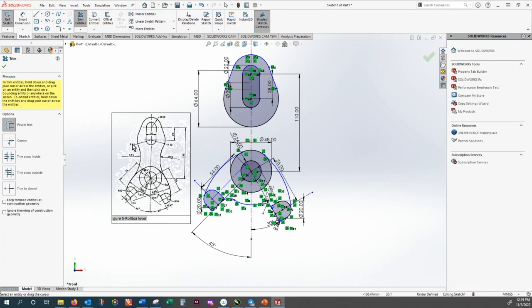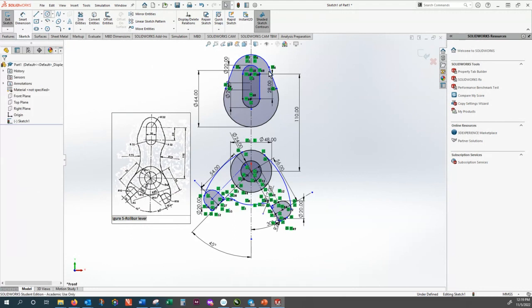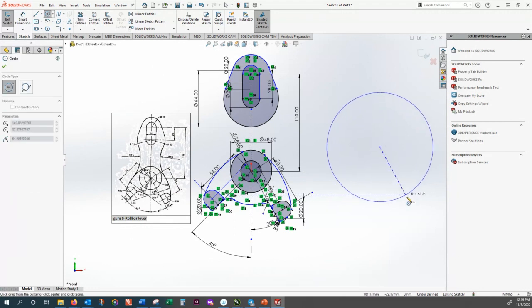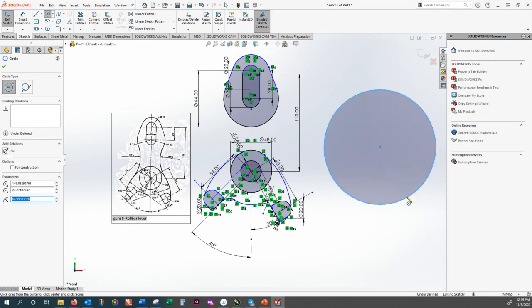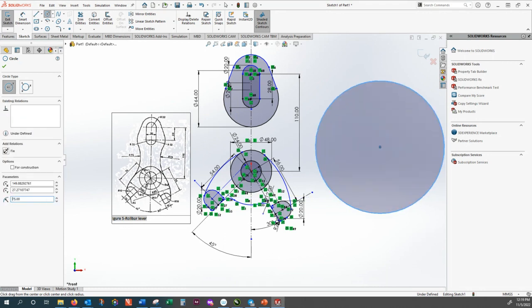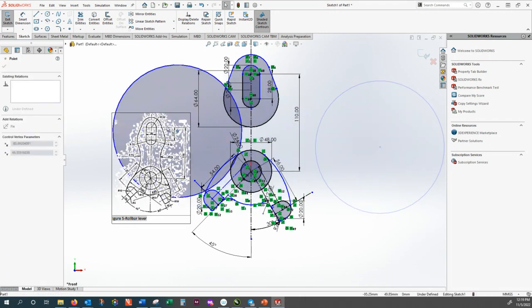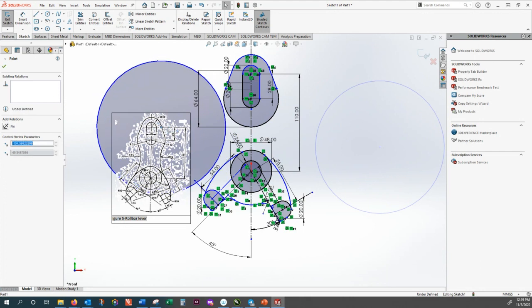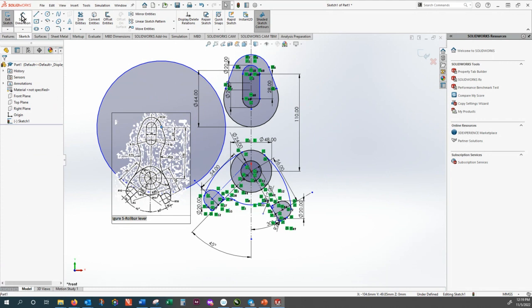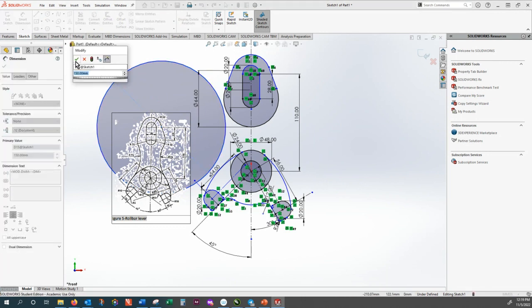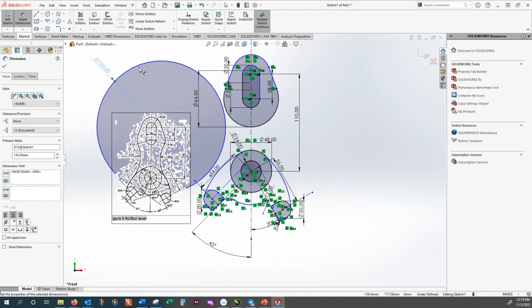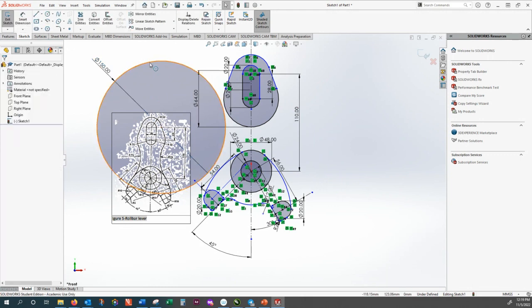The last thing we have to do is to add two arcs with a radius of 75 on both sides. So like usual, we make a freehand radius of 75. So this is not freehand, but we get rid of the unwanted things later on. So let me see if I can bring that nearby here. And once I do that, yeah, that's the fixed diameter. And let's make sure it doesn't have any unwanted relationship.